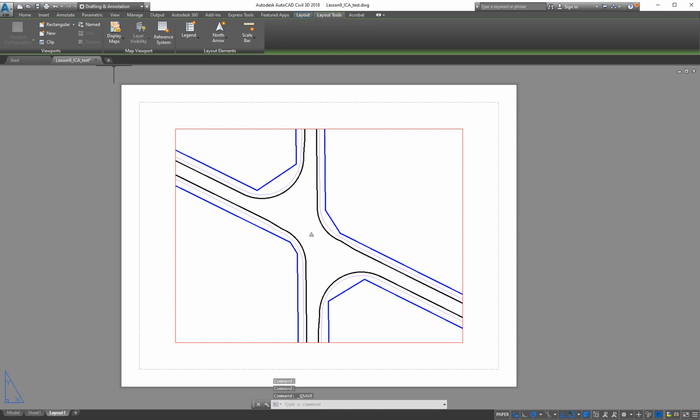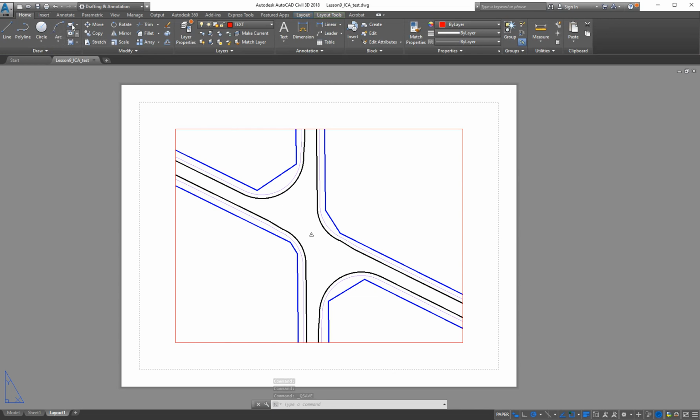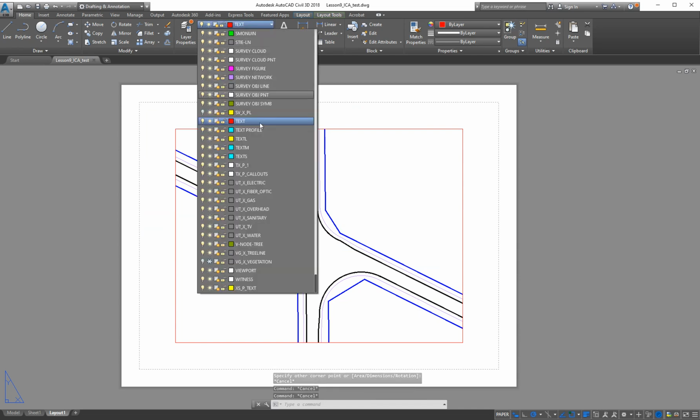And now you're going to make your own. Sorry, this is the sheet, and it says nothing around it. So let's make our own title block, right? Why not? And I'm going to make mine with the rectangle command. Oh, I'm on the wrong layers. Let's check for layers here. Does it tell you which layer to use? SH border. So where's SH border?